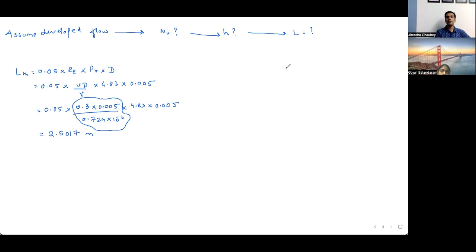If you remember, we had a discussion about the parabolic profile. Velocity is the same everywhere, but after some distance, the velocity forms a parabolic profile. It is very important that this velocity profile is formed well before the thermal profile. Otherwise, the thermal profile will never settle down.